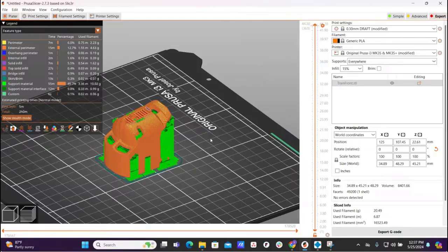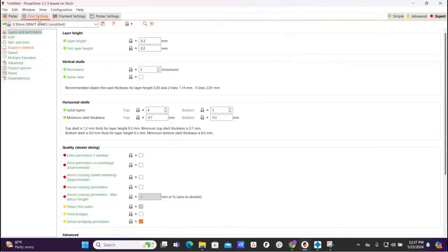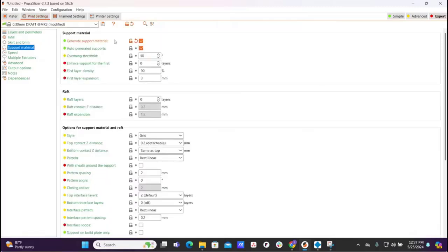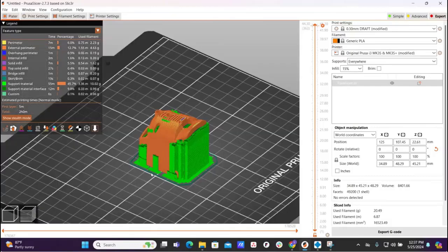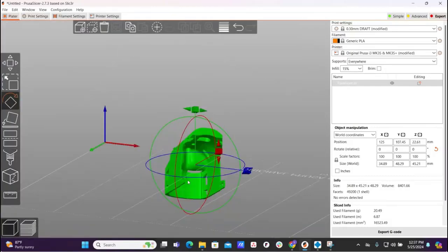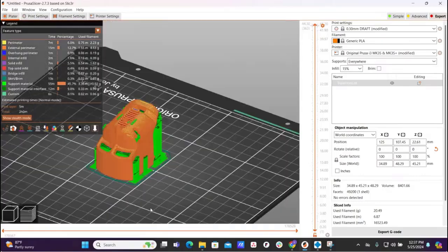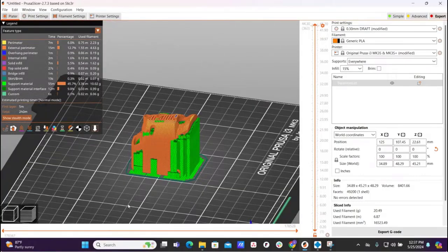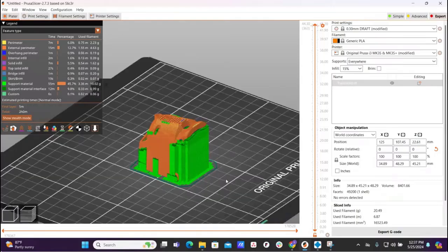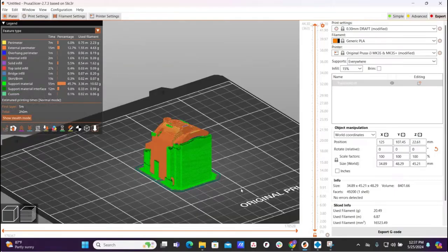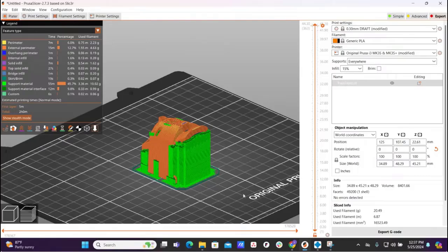So once I have all of my settings here, right? We didn't go over support material, but it's important. There's a checkbox that does generate auto supports, and it works. And maybe you don't want as much support as you have here, just everywhere. You can delete those, but again, we're talking about just getting started, getting prints. You can play around with paint-on supports and things like that, and you can find a way to lessen this so you have less work manually, but that's getting into intermediate.